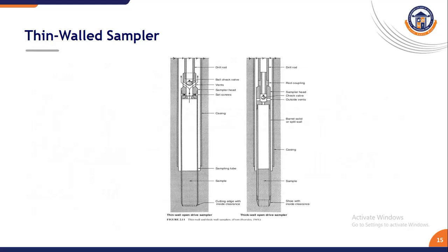Finally, the conclusion from this topic: soil exploration is essential before any construction, and different methods are available depending on the soil and depth. Sampling, whether disturbed or undisturbed, plays a vital role in reliable soil testing. Tools like the split spoon and thin walled samplers are commonly used in practice. So if soil exploration is done carefully, it ensures safe, stable and economical foundation design.